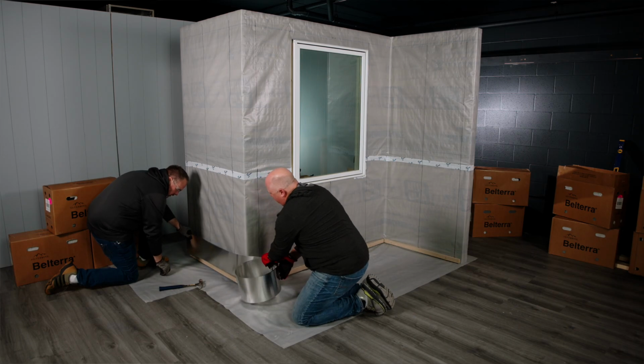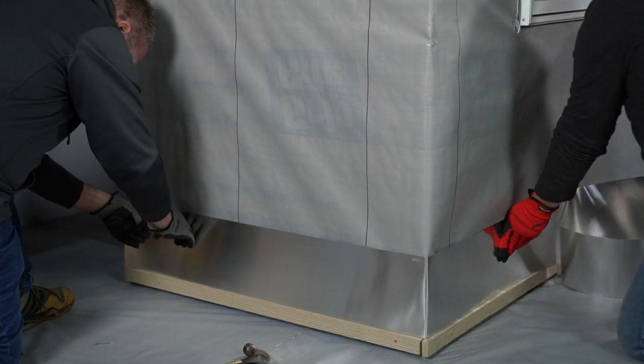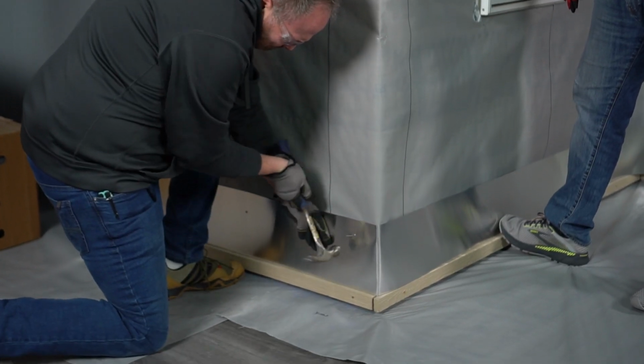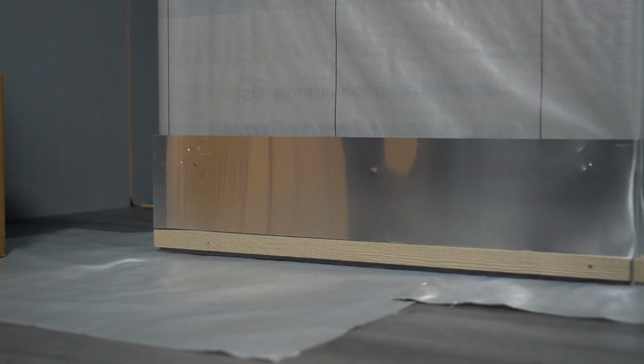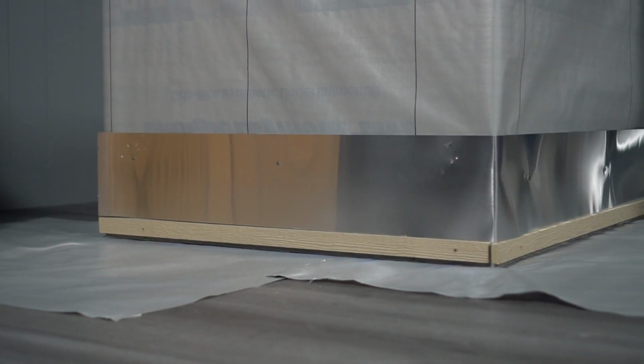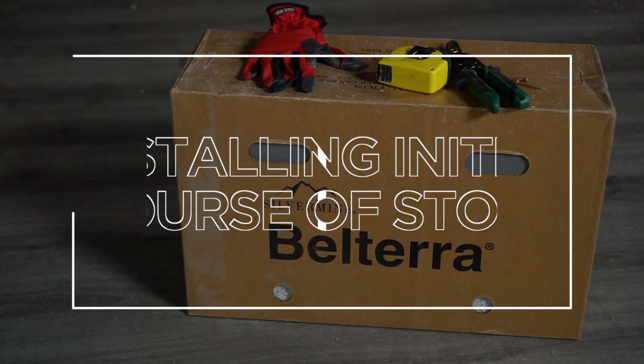The installation begins by installing a layer of metal flashing along the base of the wall. This flashing should measure a minimum of 8 inches tall from the bottom of the first layer of stones. This will ensure that the flashing will extend a minimum of 2 inches above the top of the first row of stone panels.